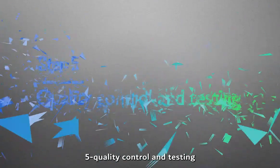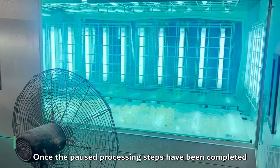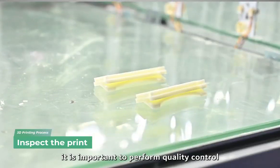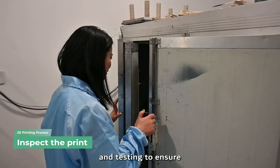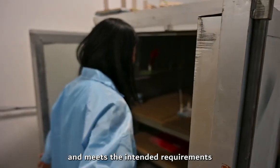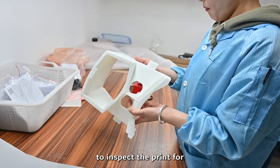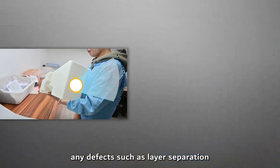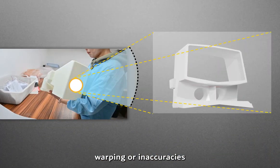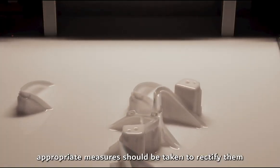5. Quality control and testing. Once the post-processing steps have been completed, it is important to perform quality control and testing to ensure that the printed object is of the desired quality and meets the intended requirements. The first step in this process is to inspect the print for any defects, such as layer separation, warping, or inaccuracies. If any defects are found, appropriate measures should be taken to rectify them.